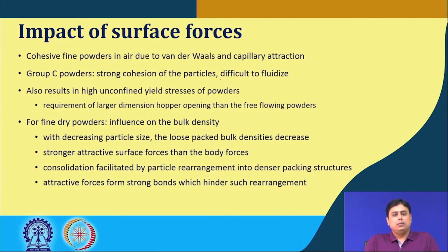So that means cohesive fine powders result when in contact with air, because of the van der Waals and the capillary attraction. This is also the reason why the Geldart group C particles exhibited strong cohesion and were difficult to fluidize, because of this attraction and the fine sizes of the particles.